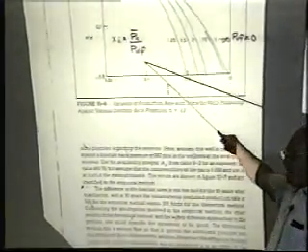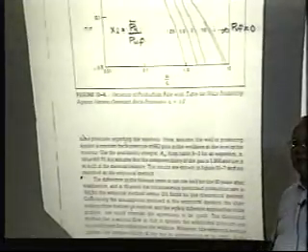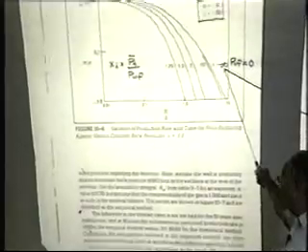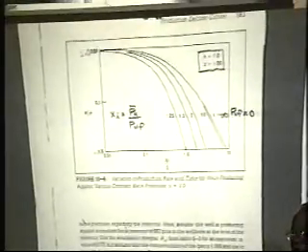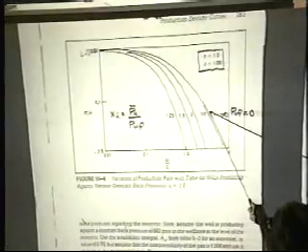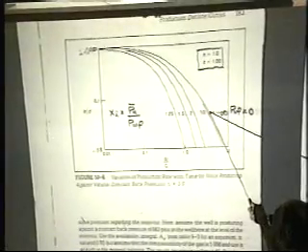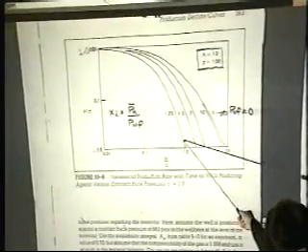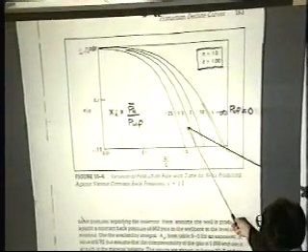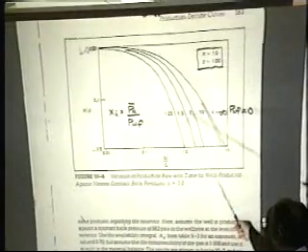This is for an N of 1. His ratio is the inverse of mine. He plots shut-in pressure over the flowing pressure, so the ratio out here of infinity would be my ratio of 0. And if you take this data here, this would exactly be a B of 0.5, and you get to approach exponential decline. But he's got the back pressure actually built into these curves for a given slope,